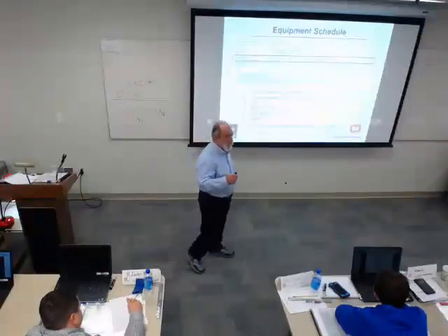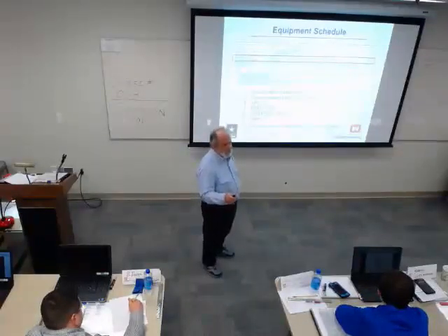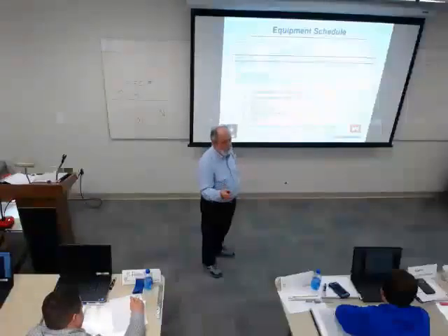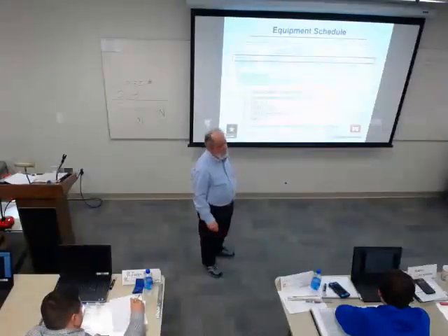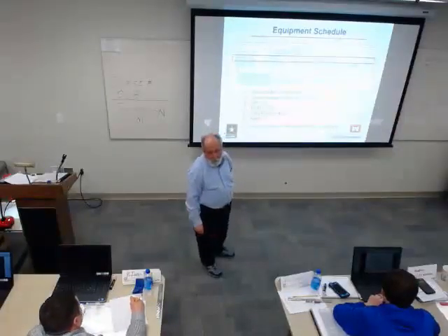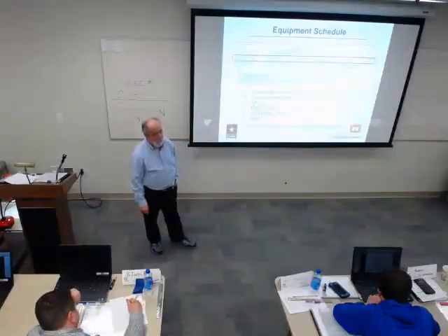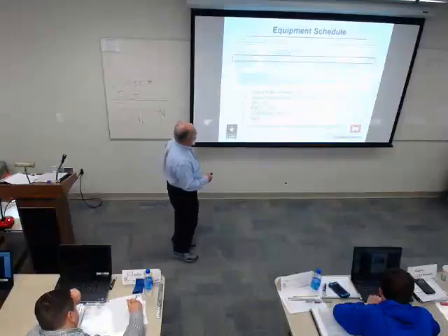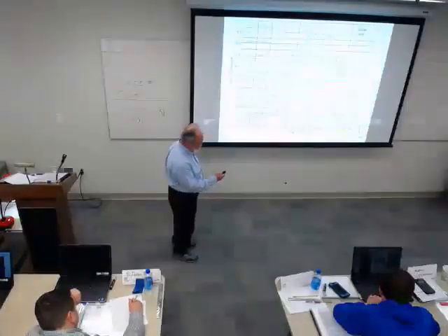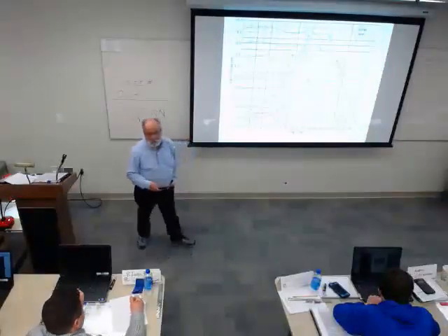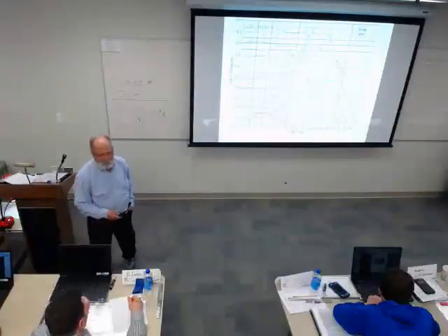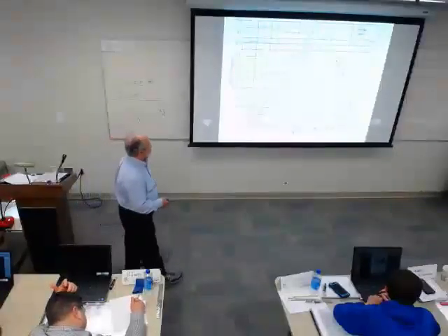So units vary, and this is one of the things you want to watch for, because you like your drops to be only the ones that are major, like coils, filters, stuff like that. You really don't want the manufacturer screwing you over on the fact that they put in a fan wheel in a not good way. There's some limits in terms of what you can do to actually fight that, but it affects your horsepower.